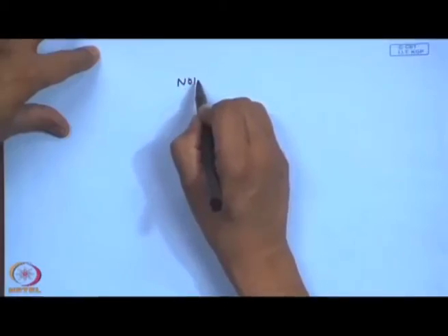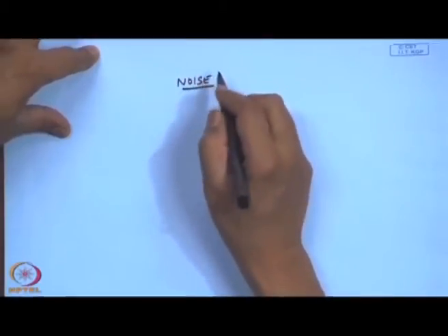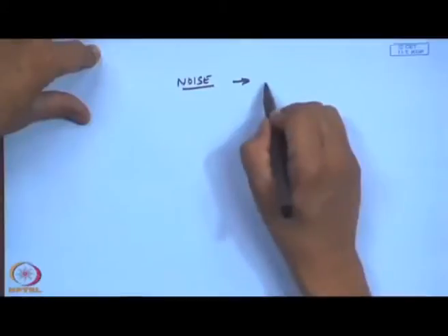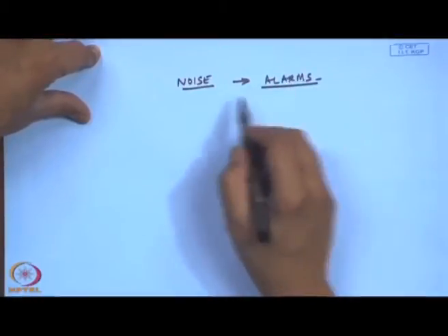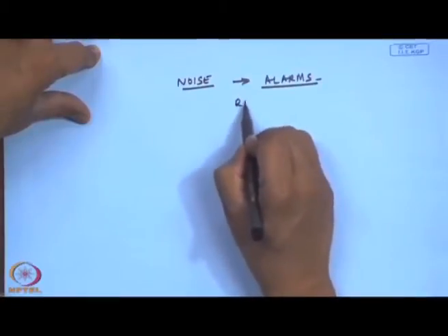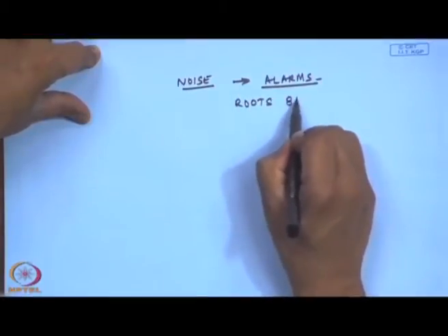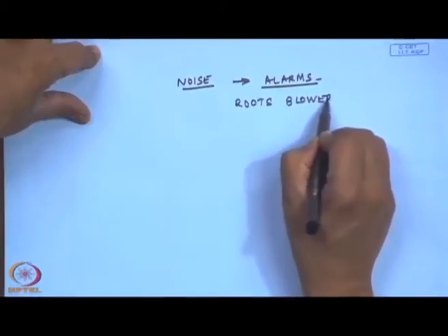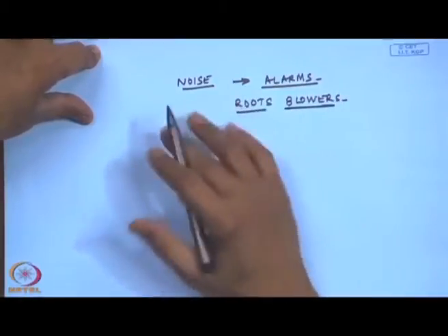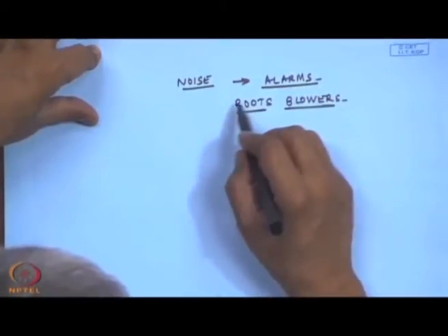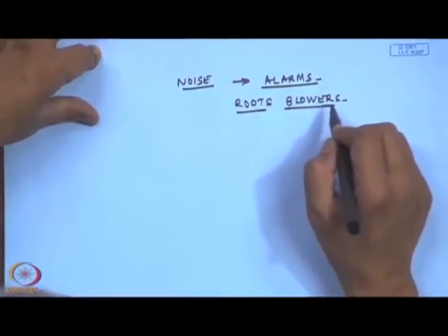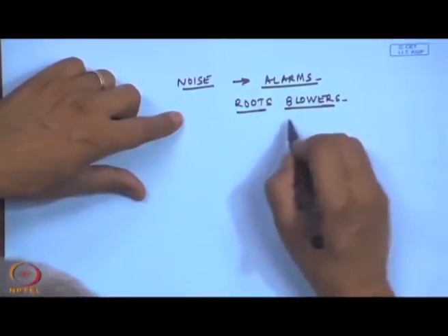Now, associated with vibration obviously is noise, but nobody uses noise as a condition monitoring tool for fans, blowers and compressors, but they definitely at high speeds, these axial flow compressors and particularly the roots blowers are very noisy because of the positive displacement nature and opening and closing of the valves, and at very high speeds these create problems and they rotate. These lobes are at very close tolerance.